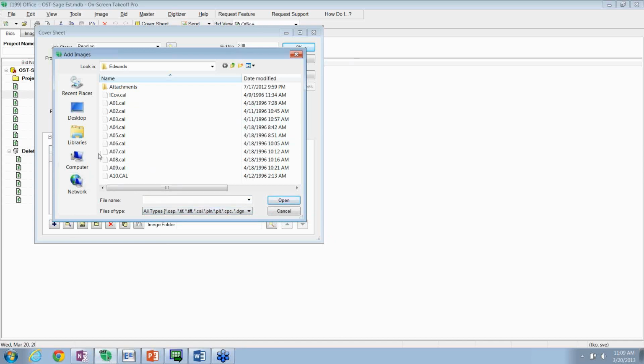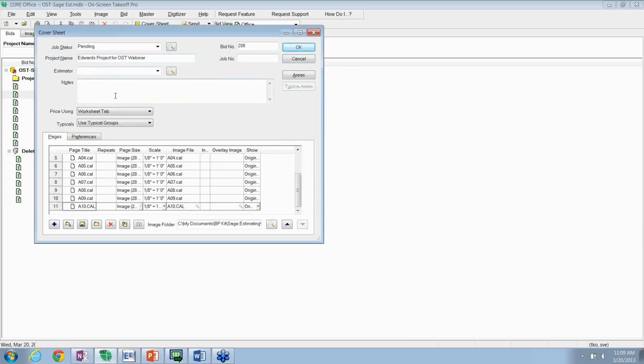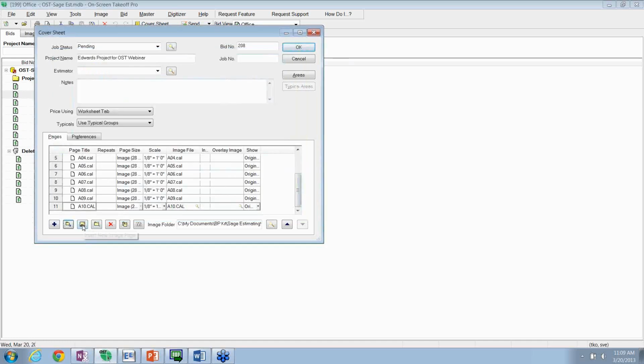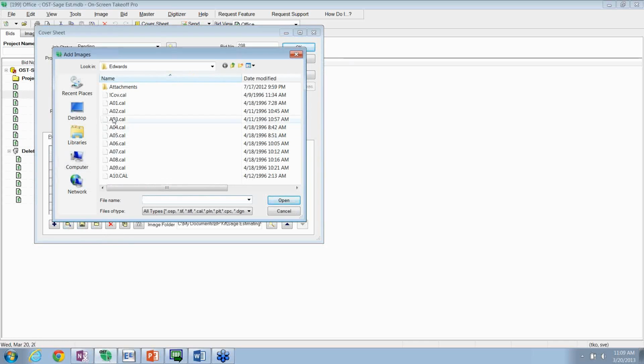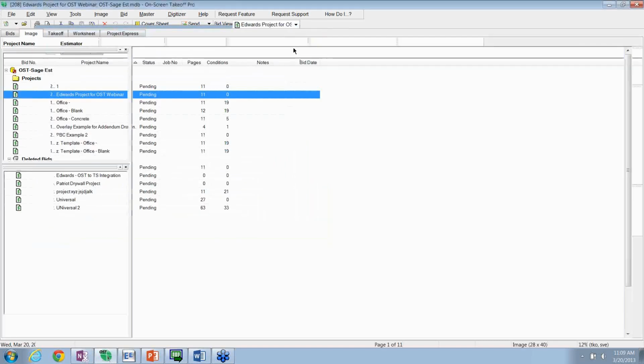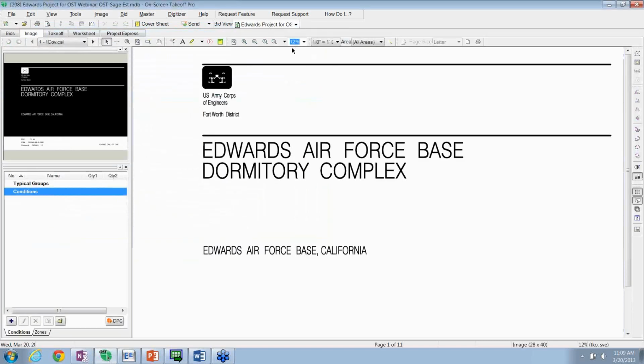When I open this up, this command I was touching on here, the second command to the right from the left, if I open this up and double-click, it just sweeps up and grabs all those files. The intent is when I use the auto add, I can click here and it just grabs everything underneath that folder. If I click here, I can pick and choose maybe individual sheets if I don't want all the plans. So the whole concept is, I've dropped the plans into my project, I hit OK, and at that point it takes me right into the next screen.